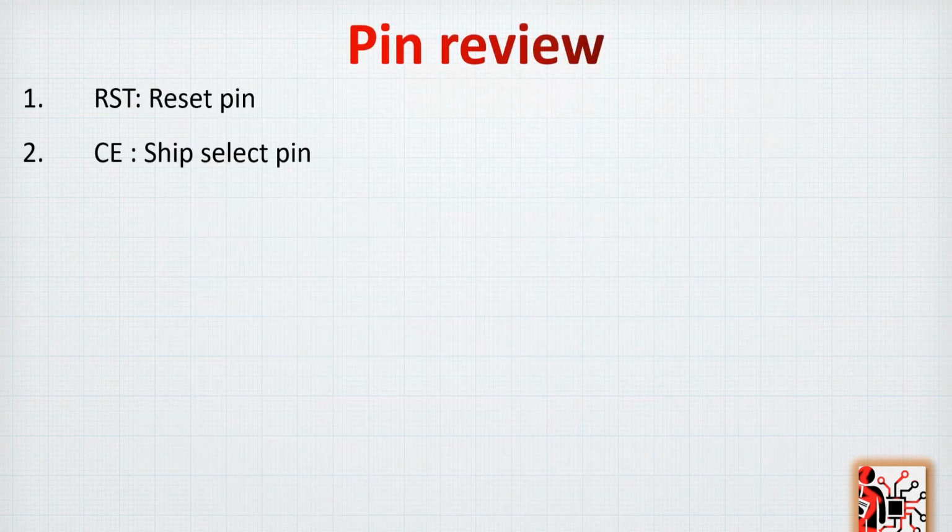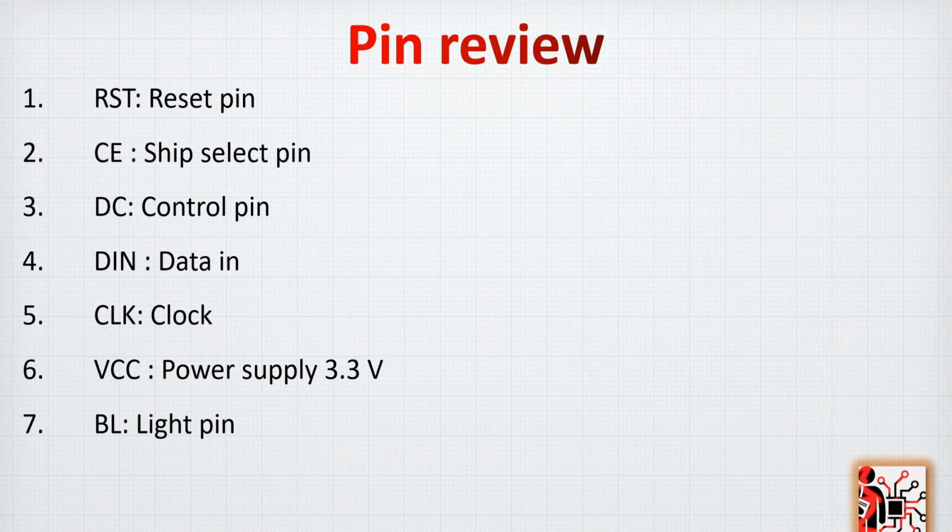So let's go back again quickly. Okay, the BL pin is the one that can turn on the backlight of the Nokia, so we are going to use this one later. And finally we have the ground pin that will be connected to our ground. That's really good.